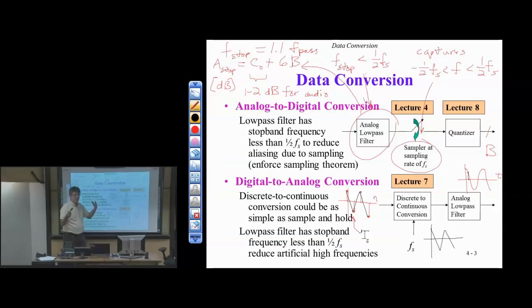I have a notion of a sampling time because I'm going to use that to reconstruct from this discrete time digital representation to a continuous time analog representation. So now once I know that the distance between adjacent samples in my discrete time signal is the sampling time in seconds, that helps me convert the discrete time axis to the continuous time axis.